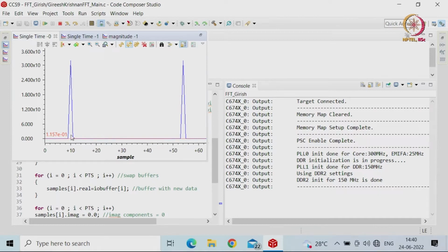So, you are generating the 10 hertz signal, which you have computed without knowing what the frequency component of the input signal is. Here we know it. In normal cases we may not know what kind of signal we are going to get. So, once I find the frequency spectrum, I know what frequencies are present, but I should know at least what sampling frequency was used.